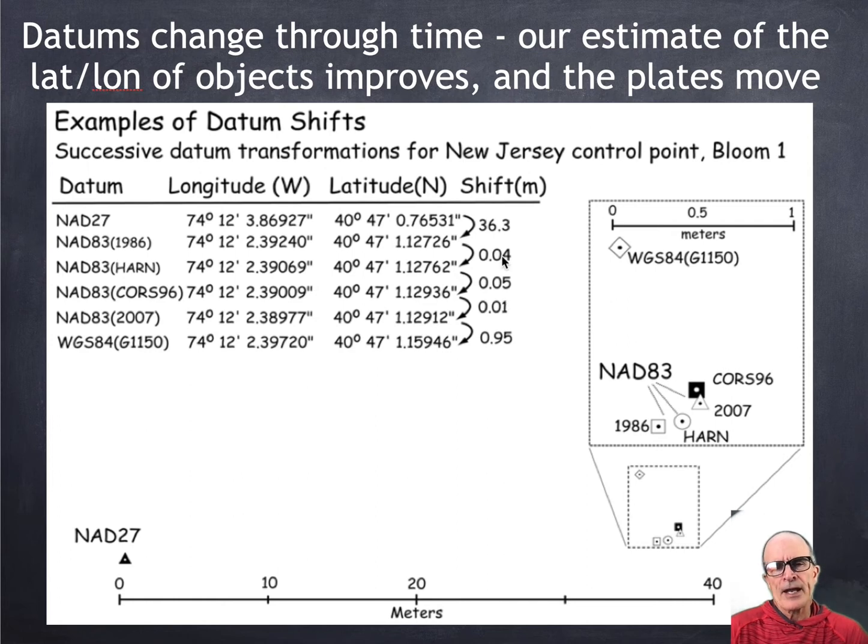But it's gotten to the point now where everybody's using GPS. It's relatively easy for them to calculate new locations, so we will switch to something compatible with the rest of the world. The rest of the world was a little behind us in the adoption of these dynamic geodetic datums, and so they just said, look, we're going to all switch to this ITRF, this standard location that we can then pool resources to measure better.